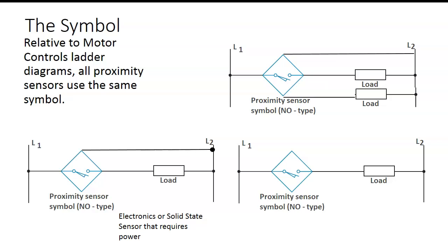So these are powered up. When these things turn on, you're going to get almost 0 volts. You're still not going to get 0 volts unless they have a relay output, because they're solid state. They use electronic devices like triac outputs. Some people call these solid state relays because they will switch on and pass AC, which is pretty neat. They still have to drop a voltage because they're not a switch, they are a semiconductor. We're going to get down in the millivolt range here on a powered system.